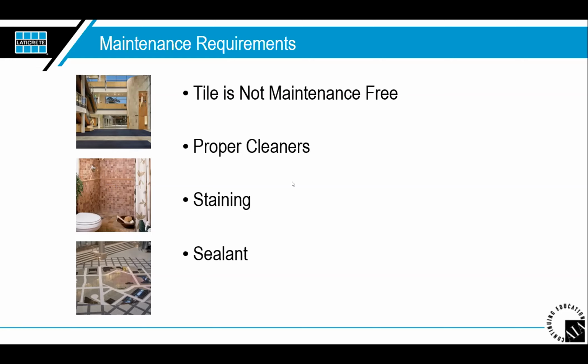Portland cement grout, for example, those sanded grouts we were talking about, some tile and some stone can be stained by a variety of materials. So sticking to one that you want to use, not switching back and forth, is going to be a big deal. Choose the proper product for the installation environment, and specify the highly stain resistant grouts we were just talking about. If you're going to go with a cementitious or Portland cement product, go ahead. If it has a sealer built into it, that should be the new standard. That is going to give you as much as you could possibly get on that side of the fence.